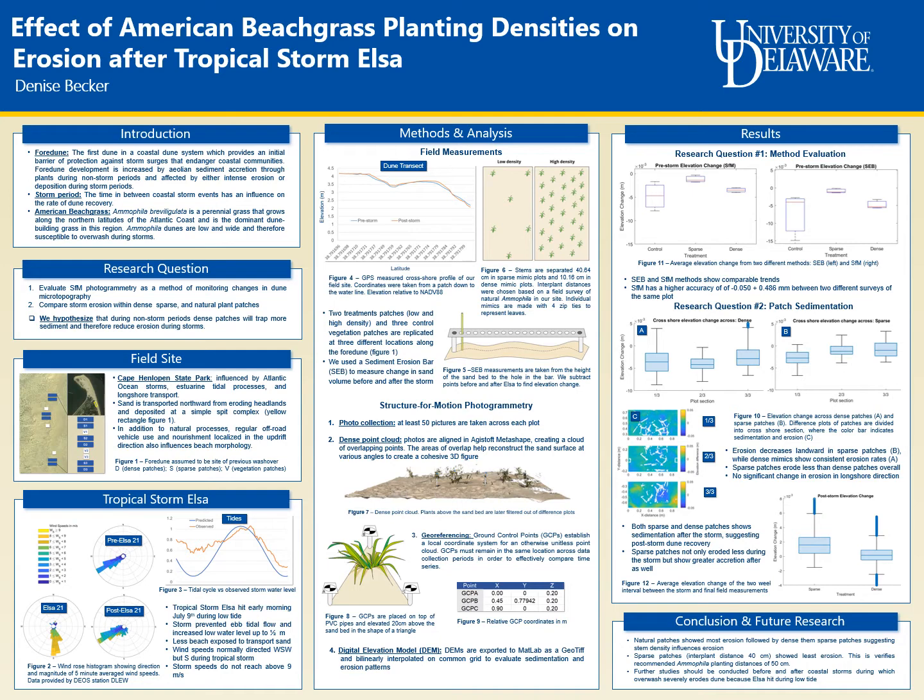Dense point clouds, as shown in Figure 7, assigned with ground control points shown in Figure 9, allowed us to make digital elevation models which were further processed in MATLAB. The models were bilinearly interpolated onto a common grid, which allowed us to compare sand volume across different periods in our study. Our results show sediment erosion bar and photogrammetry workflow produce comparable trends with photogrammetry having a greater accuracy.